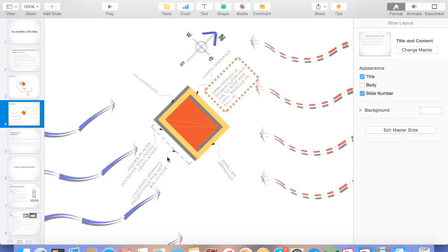It would be better even if we could give leeward shading, because then the hot air coming out just rises up from the louvers. We don't have to do anything for that, and automatically the pattern of wind flow is formed, so it can achieve really great levels of comfort. And if we have a small water feature along with this in this area, it would help us even better to achieve a better environment.